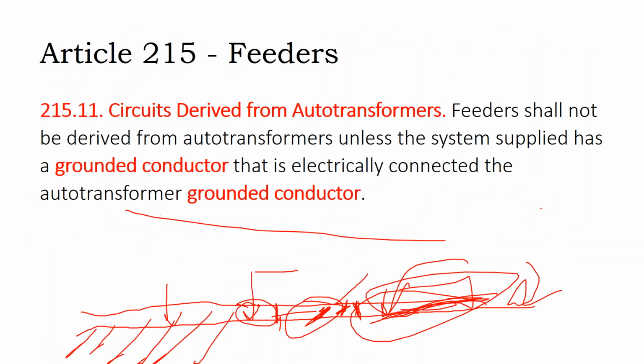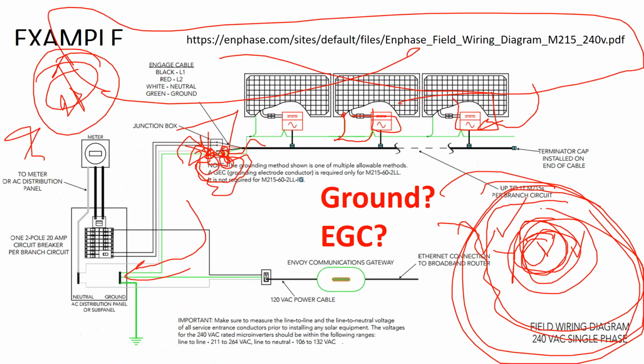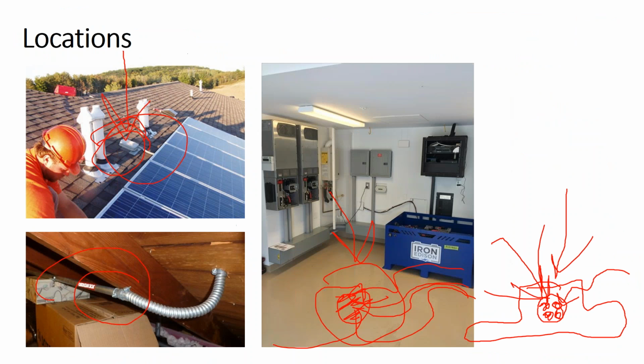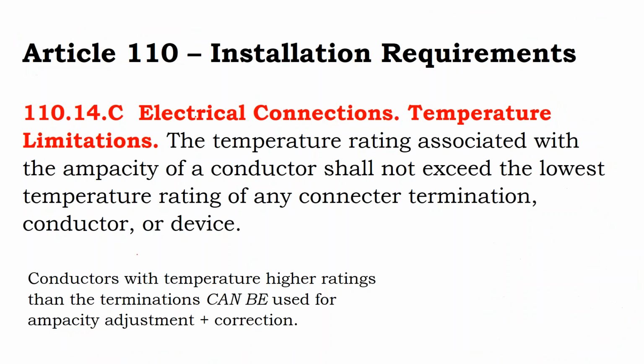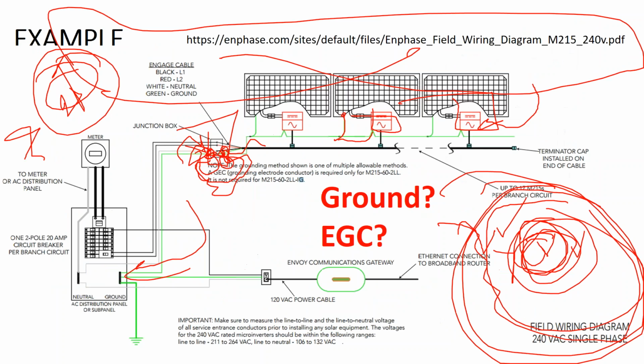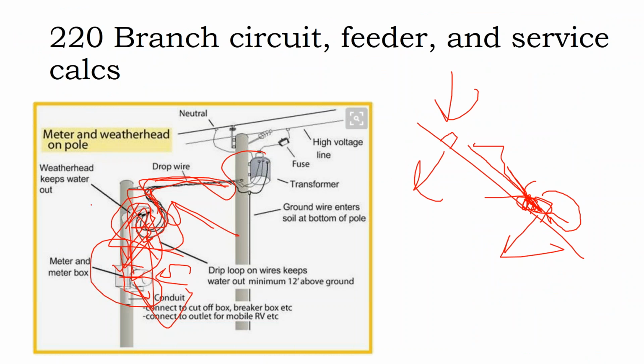So on a past picture we had way back, now we see this box. It's located kind of towards the top of the roof, and we're coming in through the bottom of it, for the same reason that you have these loose conductors coming off from the utility transformer into the home, to avoid rainwater runoff. But it's usually this stuff like what meter box does the utility want? Are we going to go in an overhead or underground service entrance? Requires some local customization.